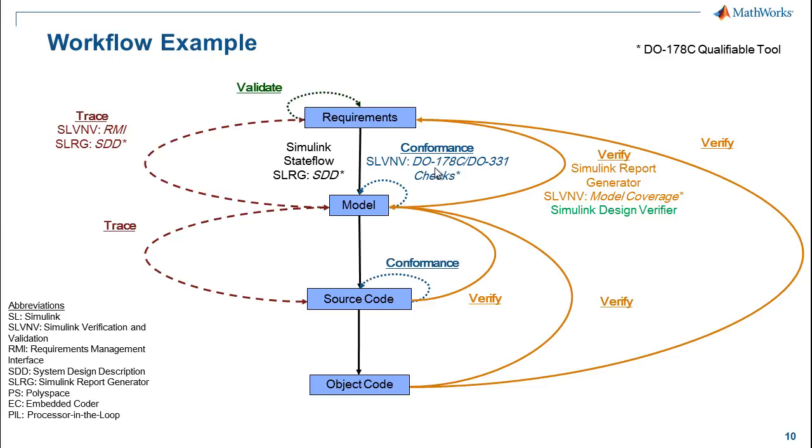All right. But then the question always comes up when we're testing, how do you know really when you're done testing? And so the third feature of Simulink verification and validation is the measurement of model coverage. And I actually suggest that model coverage is the best metric that we have as far as testing completeness. I'll quickly talk through an example. Imagine that you have a bunch of requirements, and for each requirement you have at least one test case. And we execute these test cases against the model, and in all instances, the model gives us the same as our expected output based on the requirements.